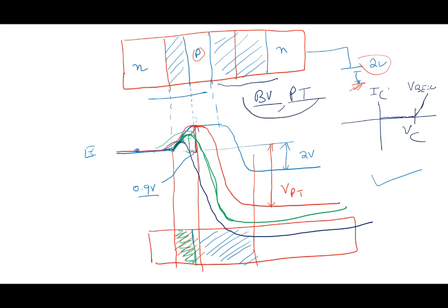So when you're designing a transistor, you have to make sure that breakdown doesn't occur at whatever is your maximum collector voltage, VC, whatever voltage you want to operate at. You have to make sure that breakdown doesn't occur and punch through doesn't occur. Both of these things you have to avoid. So this is one consideration when you're doing the design. By choosing the base width and other things, you have to avoid both of them, breakdown and punch through. Then you design and optimize your base width and things like that, but you have to make sure that these things don't occur.